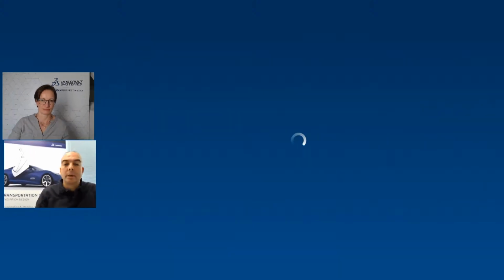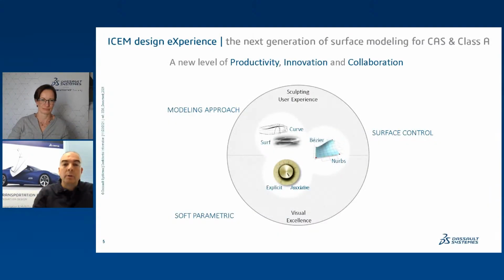And last but not least, you have this kind of tuning possible if you want to work with explicit modeling. So dead geometry, never updating, you can. And if you want, at the opposite, to always update like in traditional CATIA, you can also. And if you want to do something in between, you still can. This is the soft parametric tuning and update behavior. You will have the choice to perform.